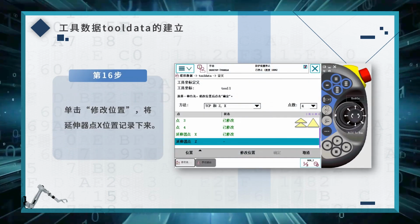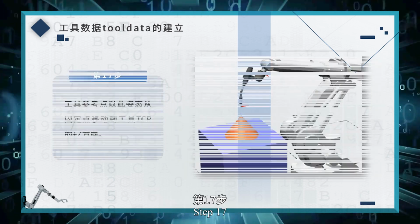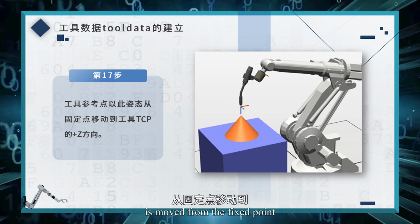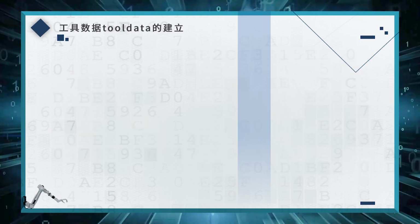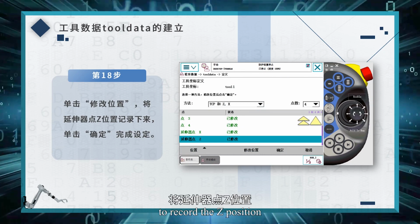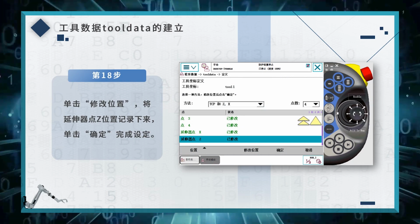Step 16. Click Modify Position to record the extender point X position. Step 17. The tool reference point is moved from the fixed point to the plus Z direction of the tool TCP in this movement. Step 18. Click Modify Position to record the Z position of the extender point and click OK to complete the setting.